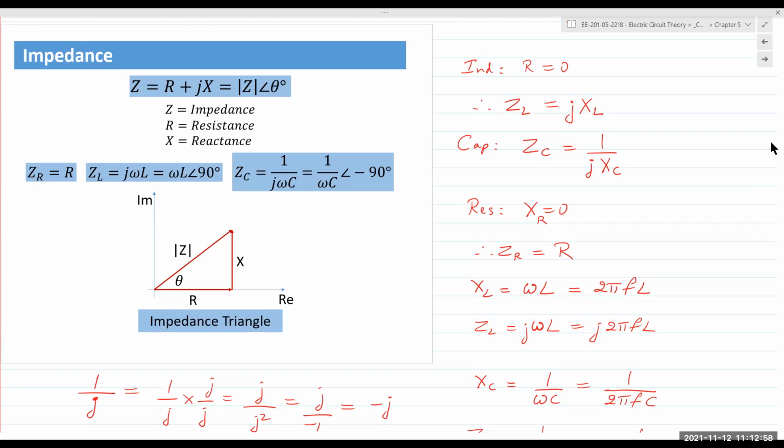Reactance has a physical basis in real life, right? It is the energy stored in the inductor and the capacitor that opposes the change in the current or the voltage. So it is not direct opposition. For an inductor, if you have current passing through the inductor, it's a coil of wire, right? So it just passes through without any problem. In real life, the inductor resistance might be a few ohms, like 1 or 2 ohms. If it's a really good quality inductor, it'd be even less than 1 ohm. Bad quality inductors, you have some high resistance.